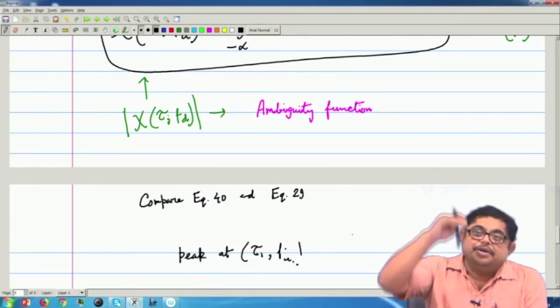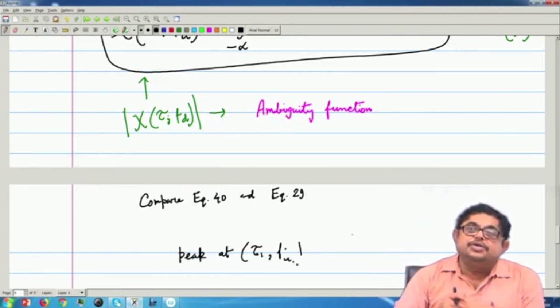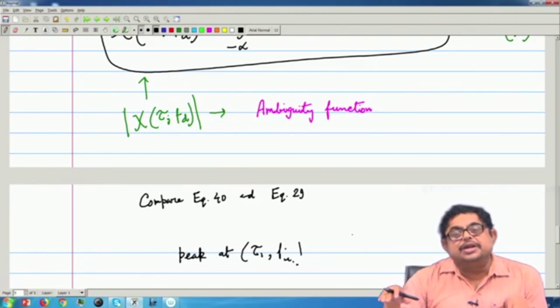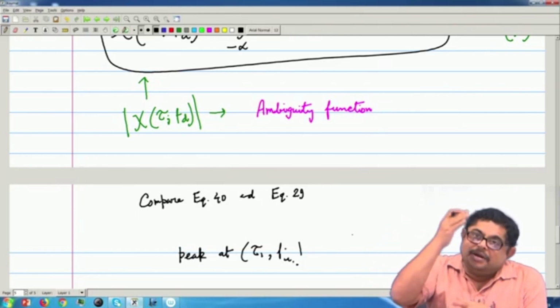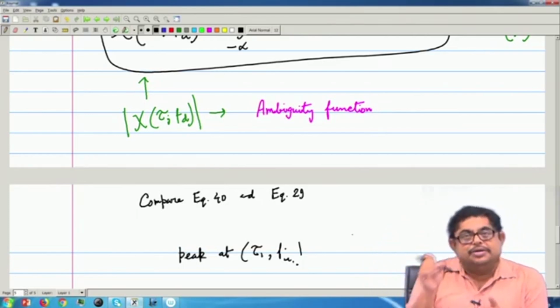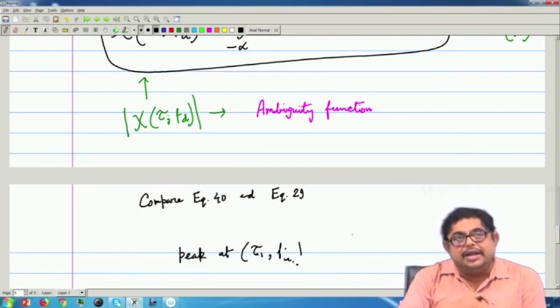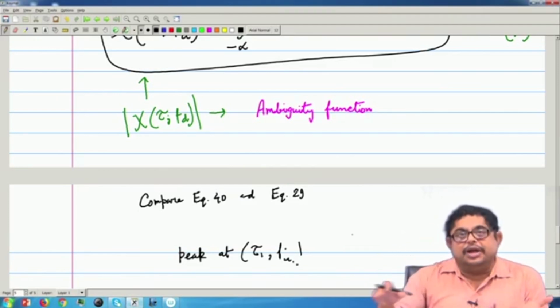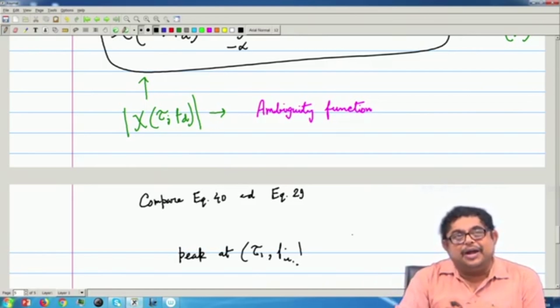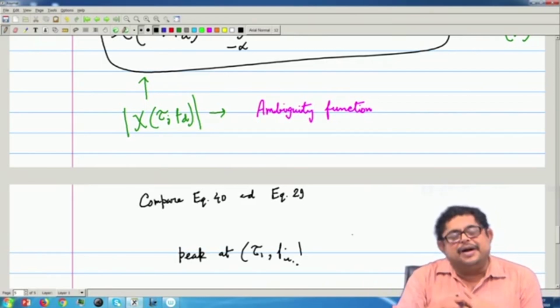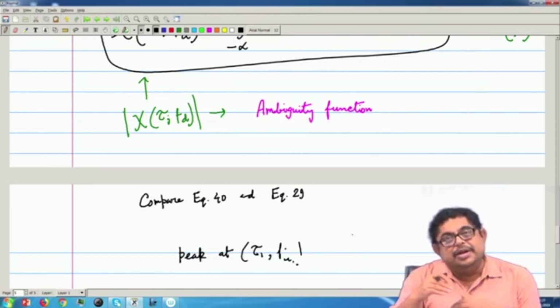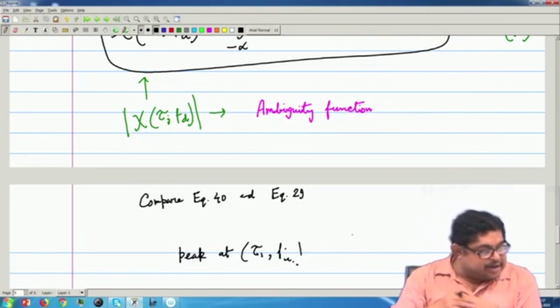That is why the peak of the ambiguity function should be sufficiently high from the nulls of the function. If we do not have that, even if we have a sharper roll off that improves the resolution, you should have a sufficient peak higher than what we can call the noise floor of the ambiguity function, so that even if noise increases, you have sufficient margin and the target will be detected.